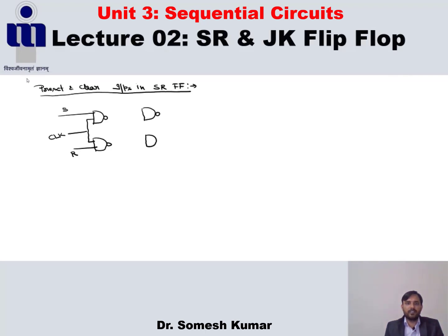So now this is basically our SR flip-flop with outputs Q and Q bar. With this NAND latch, I am connecting two other inputs, the asynchronous inputs. This one I am calling preset, and the second one I am calling clear. Right? So now what happens here?